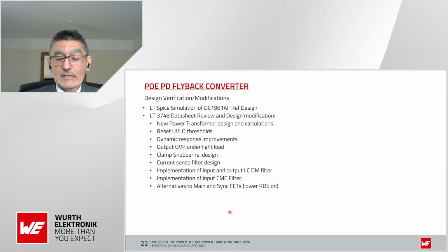We needed to look again at the dynamic response from an improvements point of view. We needed to redesign the clamp snubber, and also design the current sense filter. And as we mentioned, the implementation of the filtering from an EMI point of view. We've also looked to improve efficiency at the main and the sync FETs, to look for alternatives to those in the reference design, again for a lower RDS(on), I should say. So all of these are key aspects that we need to follow in order to optimize the design for the design requirements by the customer.